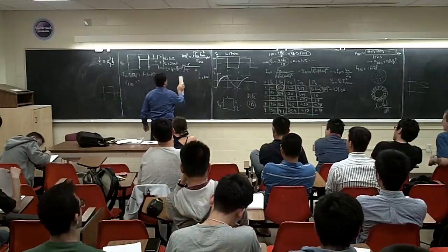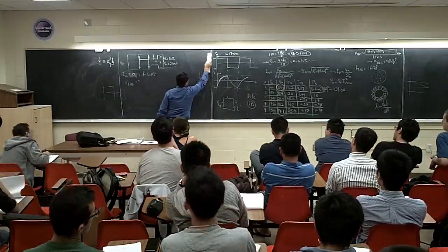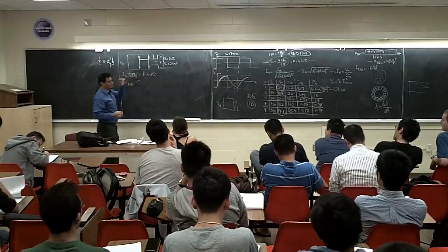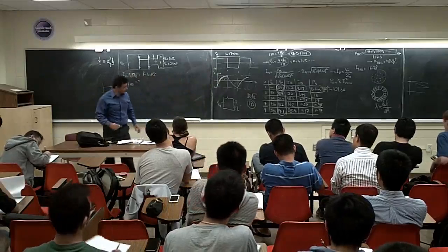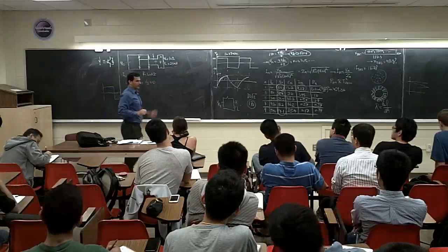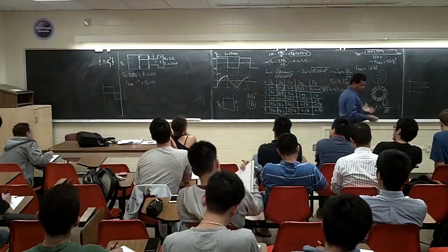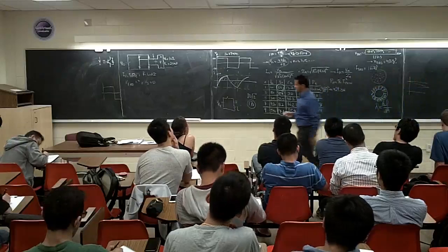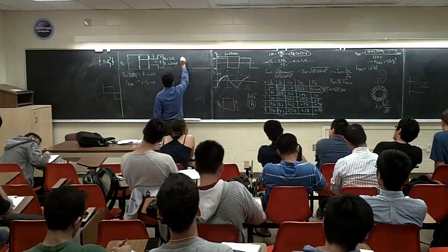Again, this is 60 hertz. We want to have 9.27 amps at the output for this, and we want to have a V30. We want to eliminate, we call it harmonic elimination. We want to get rid of this third harmonic in this circuit. So what should I do? We talked about this one. That was again a full bridge, but with what kind of output? The output voltage was like this.